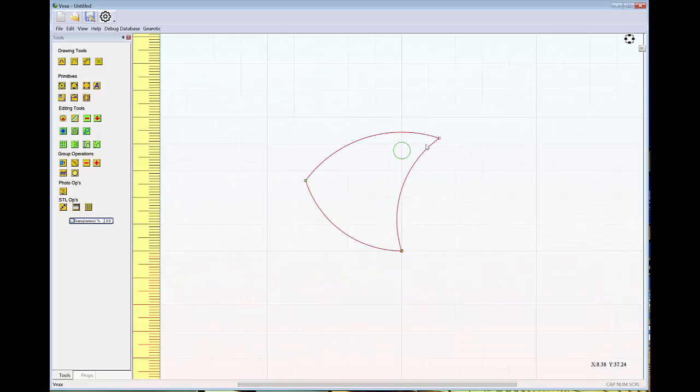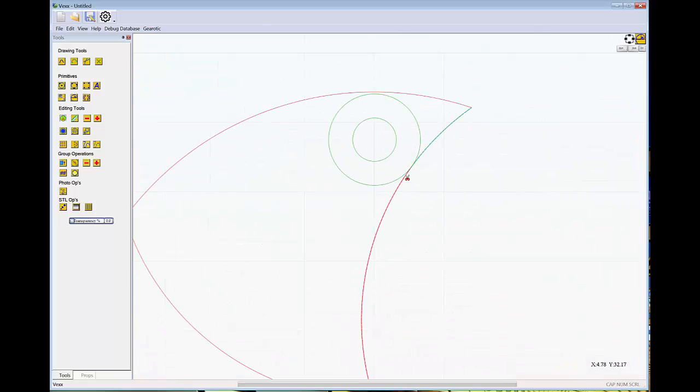But you want to round off the edge of your vanes so that this can tuck in without interfering with the next vane. So I'm going to draw a circle centered on our pivot point of this vane until it touches the contour of this curve. And now I'm going to go back to my scissors, and you can see that I cannot, although it did intersect at this point and the scissors now recognize that, we're not there at the top point.